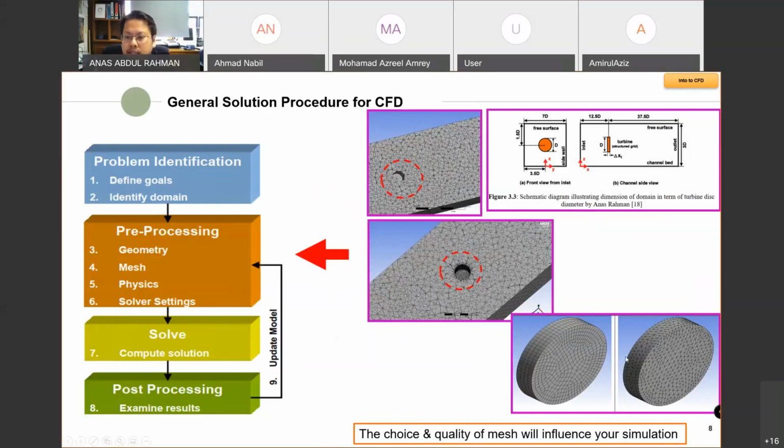Okay, this is unstructured grid, and this is structured grid. See the difference between structured and unstructured. Unstructured, it formed quite nicely along the face, or maybe the edges. Sorry, this is the edges, this is the face. But because of a circular object, the circular geometry, the structured grid has difficulty in terms of the face generation.